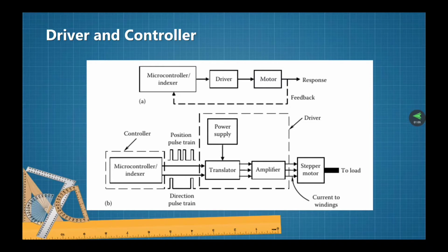A stepper motor needs a microcontroller. Okay, this is the box of the microcontroller or the indexer to generate the pulse commands, and a driver to interpret the commands and correspondingly generate proper current for the phase winding of the motor. The basic arrangement is shown in this figure.